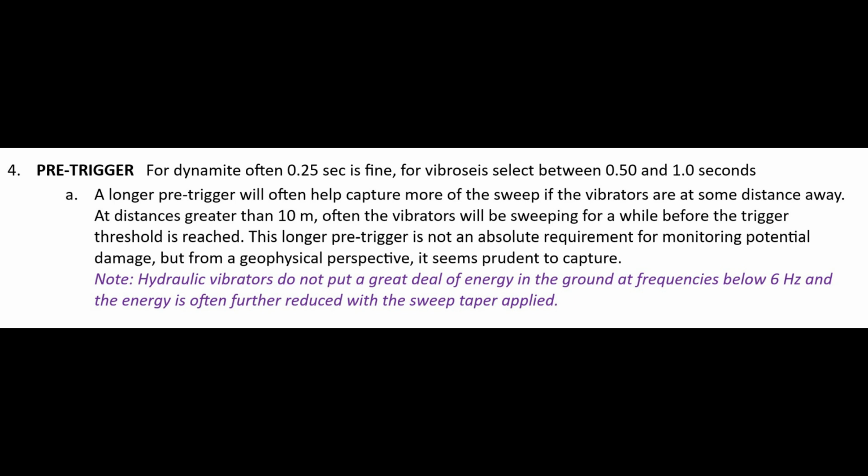Once that instrument is in waveform monitoring, it is collecting data. When it has a vibration greater than the threshold level, it records an event. Because the instrument has been monitoring and storing the data in a buffer, the instrument can go back in time and start at the selected pre-trigger time.